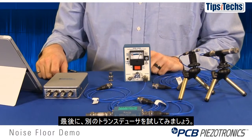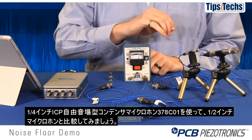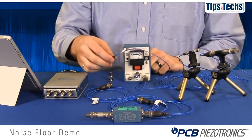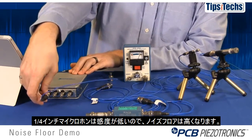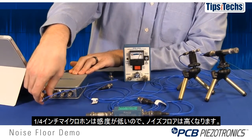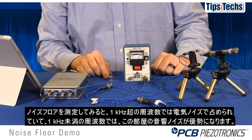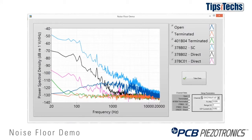So the last thing we can do is try a different transducer. Here we'll use the quarter-inch ICP powered microphone. It's a free-field condenser microphone, the 378C01. Compare that to the half-inch. Now the quarter-inch microphone has a lower sensitivity, which means it's going to have a higher noise floor. When we make that measurement, you'll see that the system electronic noise dominates the measurement above a kilohertz, and below 1 kilohertz, we're dominated by the acoustic noise in the room.